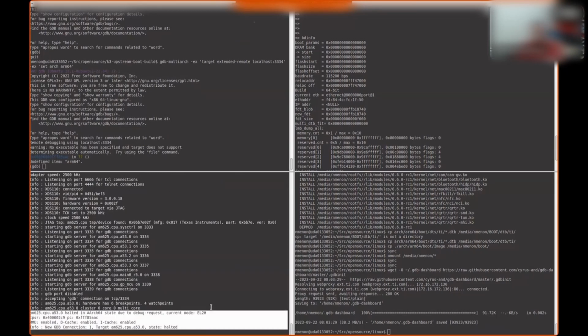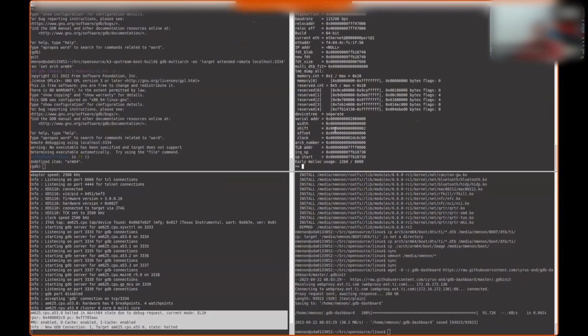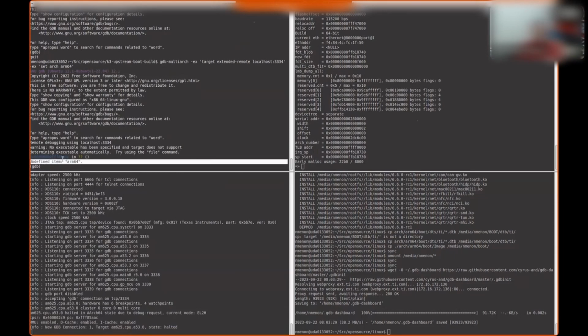And this happens automatically. Right now, even if I press enter, nothing is going to happen on U-Boot because OpenOCD has taken control of the processor. Okay, I got this wrong. My GDB has attached to OpenOCD, which in turn has halted the processor right now. It shows which address it is halted at, but it doesn't show any trace. It doesn't know how to decode the stack dump either.